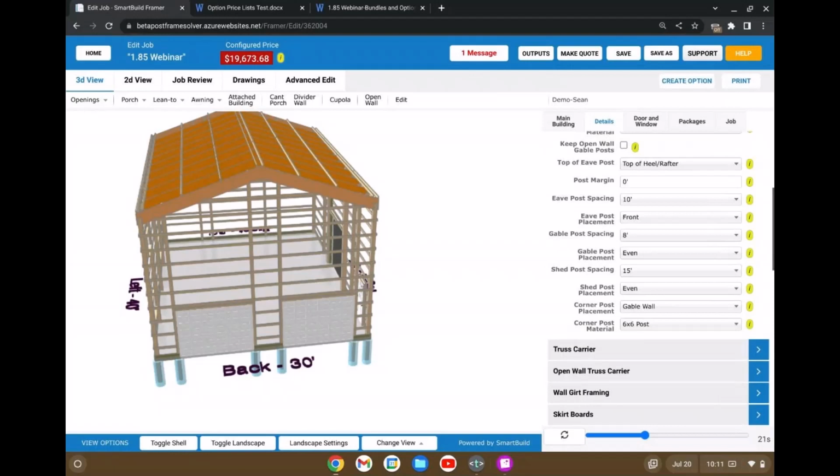Yeah. So it's similar to that issue though, because what we have here is, you said 8-foot spacing. That means the maximum spacing you want between your posts on the gable is 8 feet, and yet you've got 10 feet between two posts above those openings. So you do need a post there, and I think that goes back to what you were saying, Chris, right? Is that in this scenario you would have a post, and you would center it above each of those openings? I think so. In most cases, sometimes we'll keep the layout just so girts run the same length across there. It's not the same on every job, but definitely a post. Yeah.